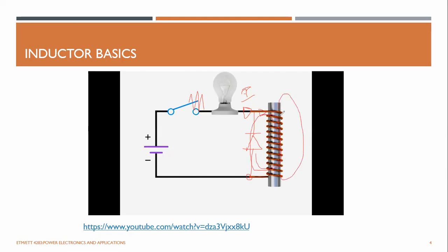While circulating through this diode, there is some power loss as heat, and there's the resistance of the wires. So the stored energy is dissipated, and these flux lines disappear over time. Otherwise, if there's no freewheeling diode, there will be a huge spark around this switch.